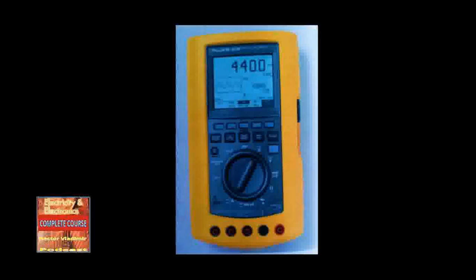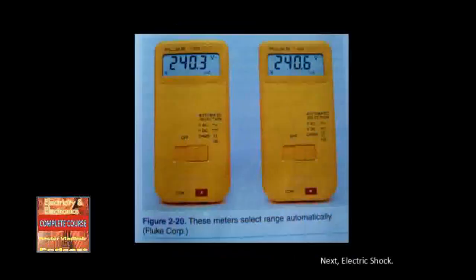Polarity is usually not an issue when using a digital meter. The meter will automatically adjust for an incorrect polarity. It will flash a message or symbol on the liquid crystal display warning the user of the wrong polarity. Some digital meters have an auto range feature. This means that it is not necessary to determine the range to select when using the meter. On these meters, this function is done automatically through the internal electronic circuitry. Figure 2-20. Resistance reading used in a DMM still requires you to disconnect the circuit from the power source to prevent damaging the meter.